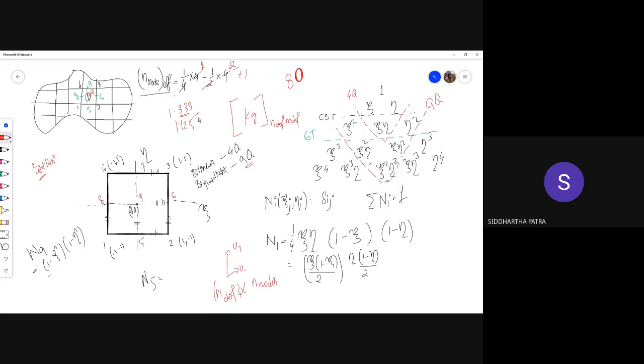So we can see that this 9th node is very costly, because obviously it is not shared with anyone. So what we can think of is getting rid of that node. In terms of polynomials that contribute to the shape function, we would get